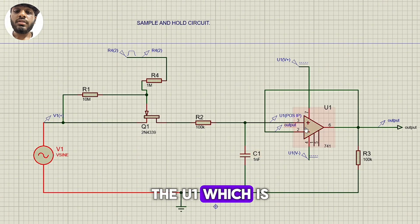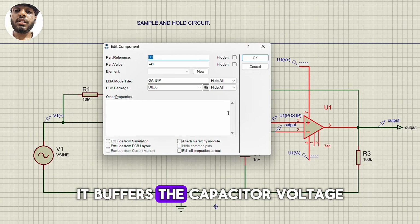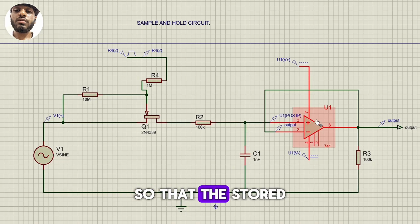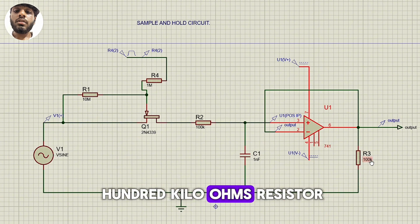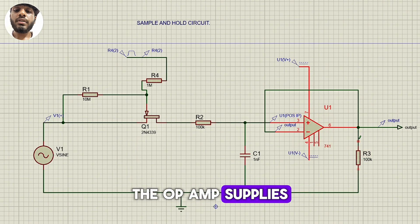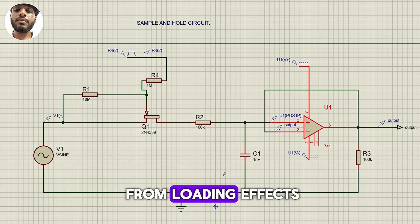The U1, which is a 741 op amp, is configured as a voltage follower. It buffers the capacitor voltage, providing high input impedance so that the stored charge on C1 is not significantly discharged. R3, which is a 100 kilohm resistor, represents the output load. The op amp supplies current to the load while protecting the capacitor from loading effects.